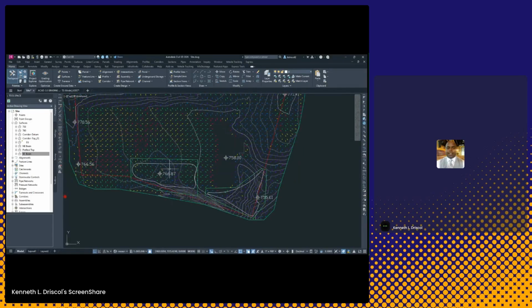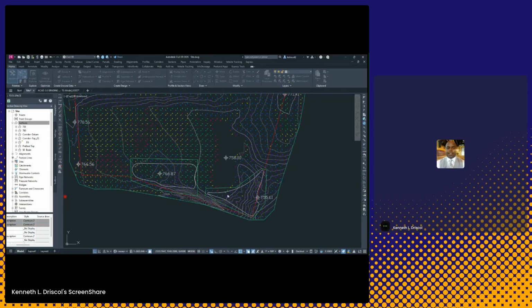Now, I'm going to come to my northeast basin. We're going to push this out, and we're going to walk through step by step to delete that. I'm going to come up to grading, create grading. This one is going to be, I'm going to create a new group name. This new group name. So that step to create this, to go into the grading group, we're going to say Northeast Basin. And again, this idea of determining the volume, and I want to compare it to 755. I want to compare it to my 760.